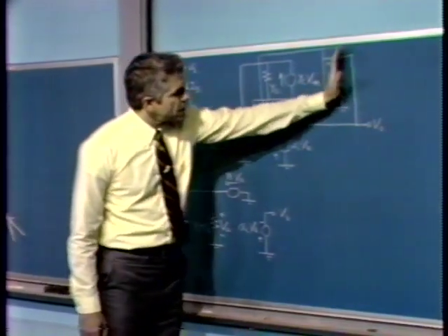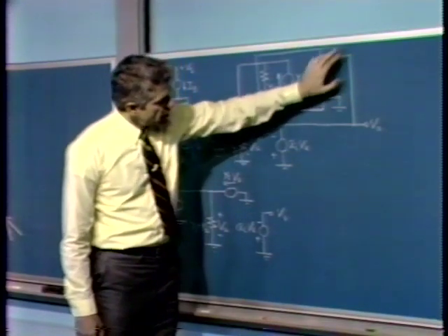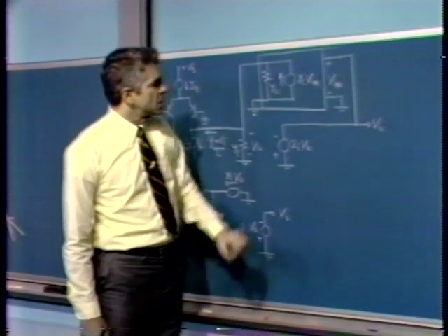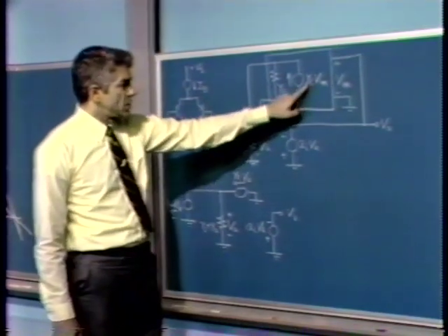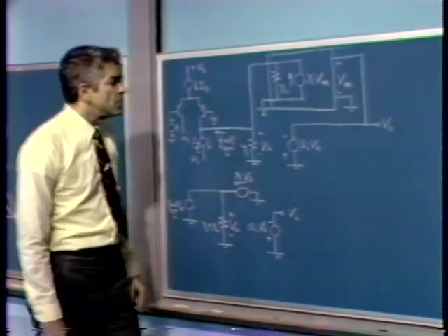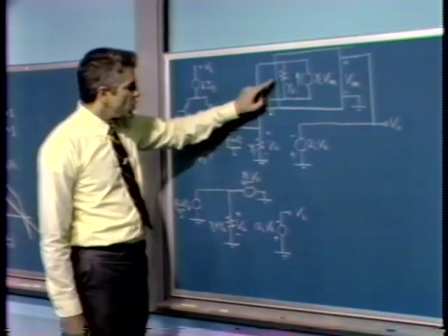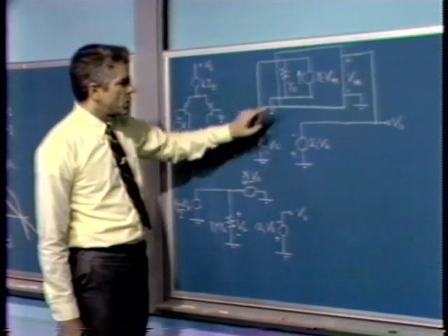Possibly by disconnecting the input port of the compensating network from V out and simply shorting it. That would, of course, disable this generator since VM would then be 0. However, we would keep the loading associated with the two-port network.